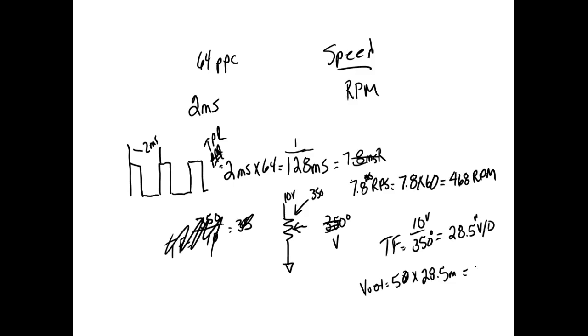I'll show y'all that on the Allen Bradley. I think I brought an 1100 over here, and I got a program that shows you how to do that. The Siemens is a little easier because you can make its high-speed counter measure frequency for you. It's really cool. Allen Bradley's, I don't know if the 5000 do that.